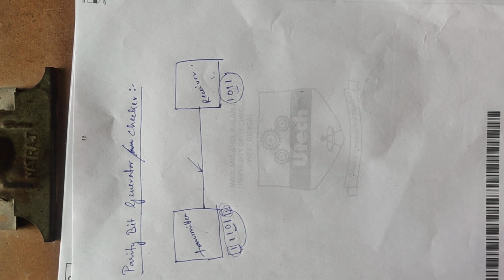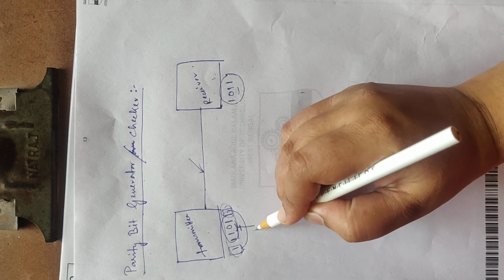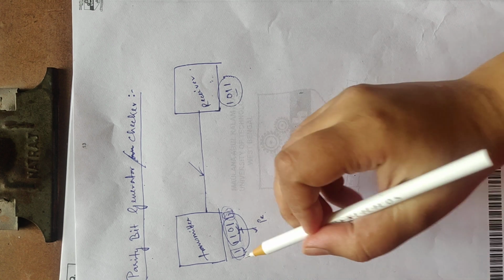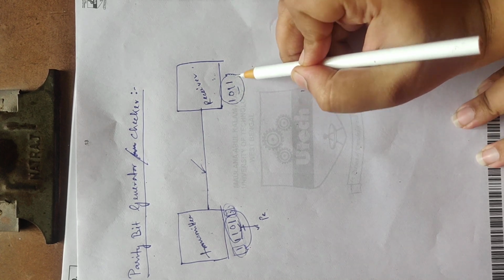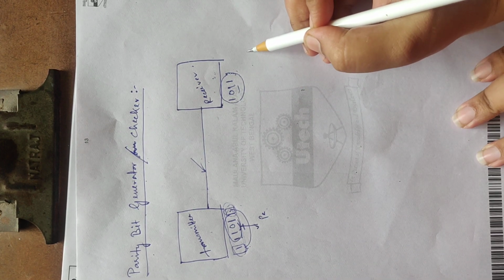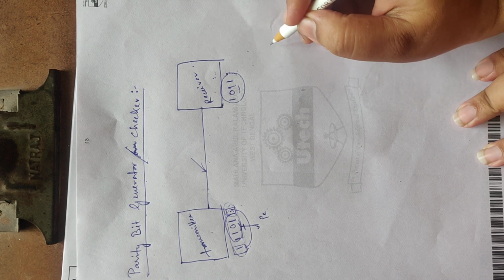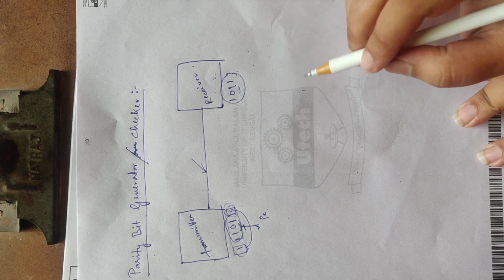But if we have a number and we want odd parity, then the number which is provided to me is already the correct number. So we need to add zeros in the front or in the back, depending upon the design. Now, at the receiving end, if the word received has an even number of ones in the odd parity system or an odd number of ones in the even parity system, it implies that an error has occurred.